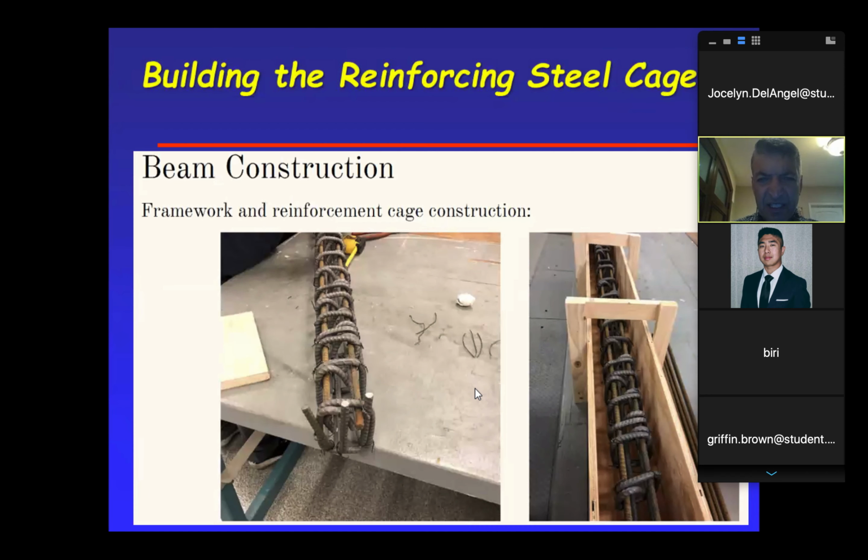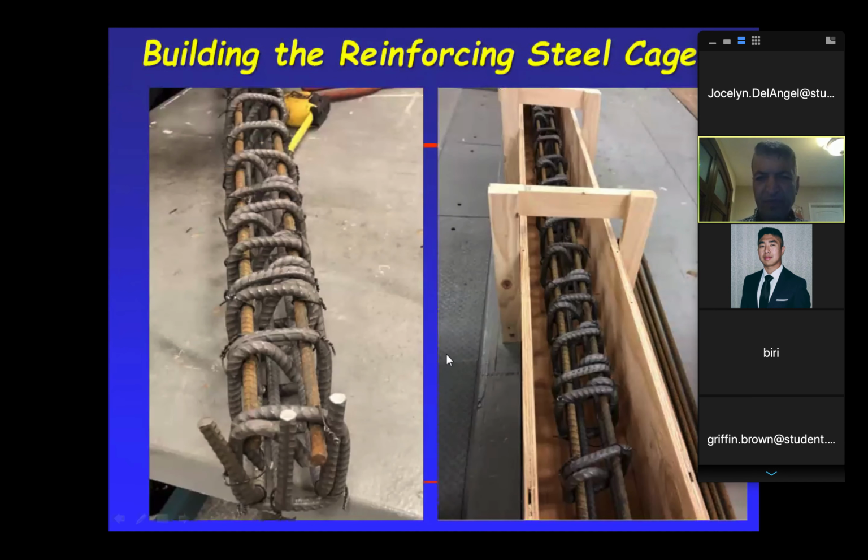And then look at these thin wires. That's what you had to tie the stirrups to these bars, using these wires right here. Okay? So this is a blown up picture of it. Again, when we calculate how many stirrups we need, you will see everybody is going to come up with an answer. We're going to need one every 2.5 inches. A lot of them. And you will see why later on when we cover that chapter.